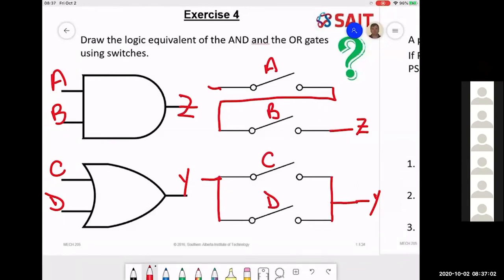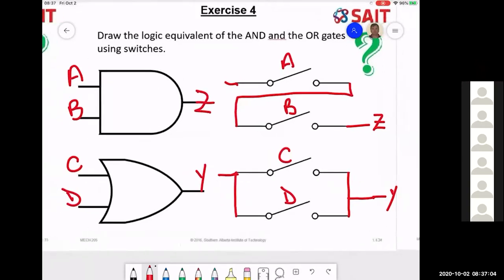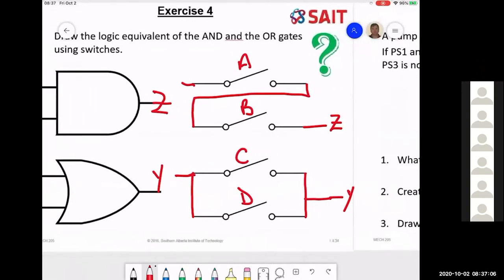I rewired my wife's cousin's house, and they had 3 horrible sets of switches that had been configured in this way. Someone had thought they'd want the lights on the stairs to be powered from either the top of the stairs or the bottom of the stairs, but they'd done it this way. So if you wanted to turn the lights off, you had to shut them both off. You might shut off the lights downstairs and then go upstairs and shut off the lights. Well, now the lights turn off and you've got to climb down the stairs in the dark. Not a great way of doing it.